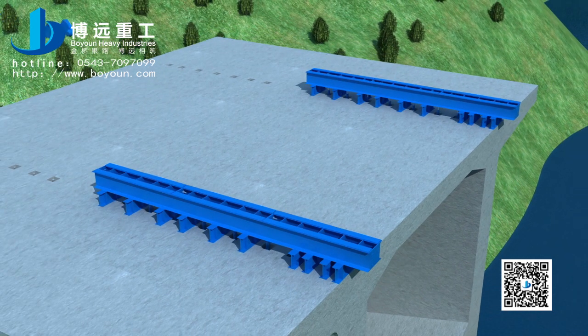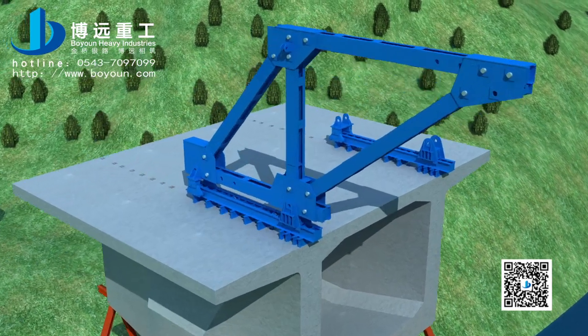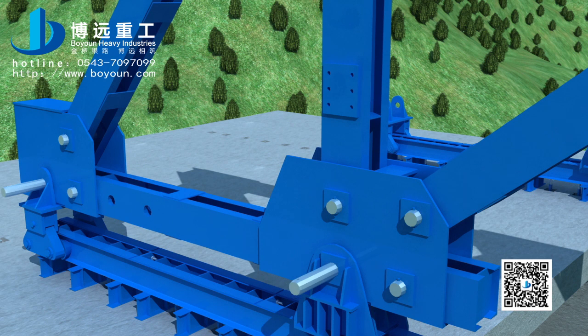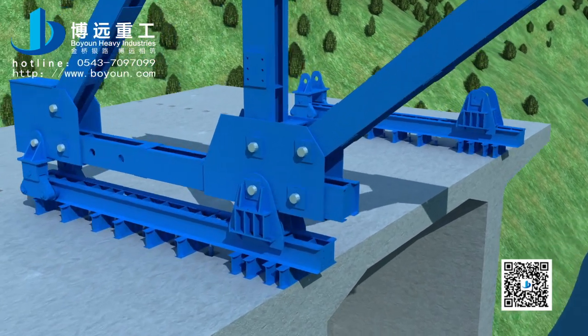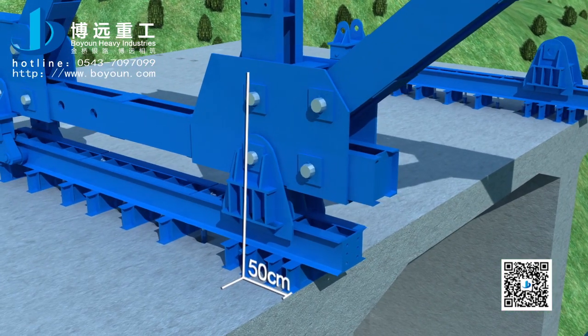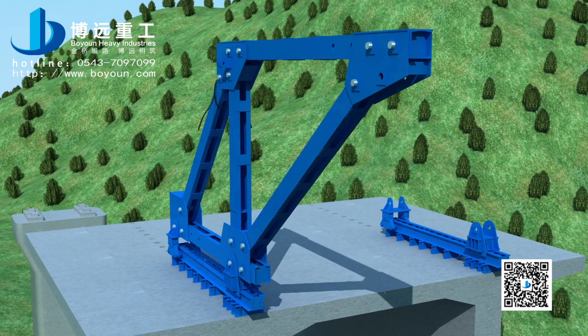Install temporary steel support. Completely install the reverse wheel fixing seat, front sliding bearing and diamond frame by pin shaft and lift to the paved orbit. Adjust the front sliding bearing to the position 50 centimeters away from the edge of the girder end. After that, temporarily fix by chain block.